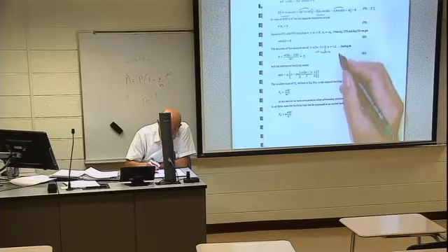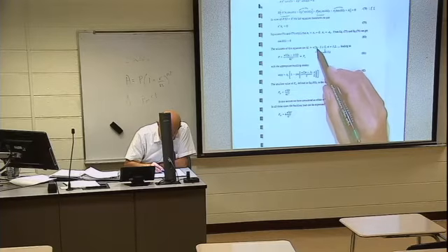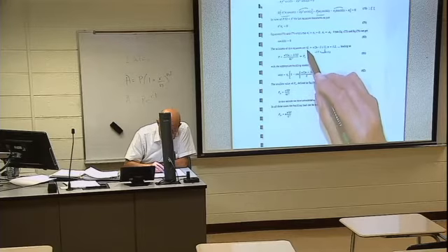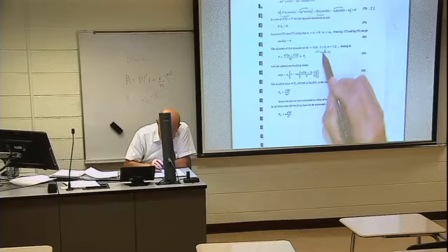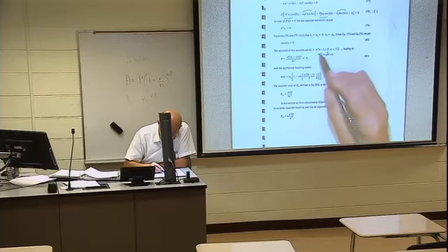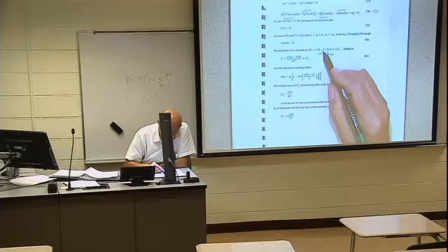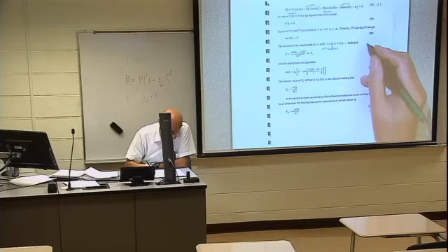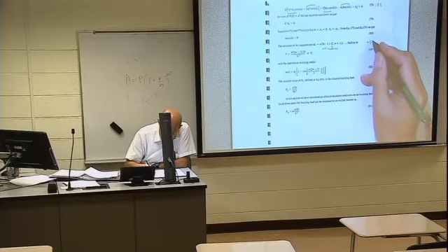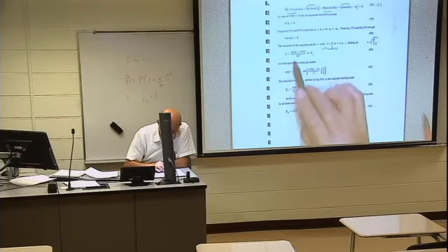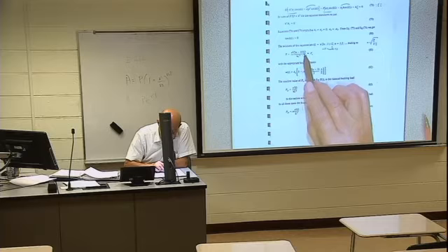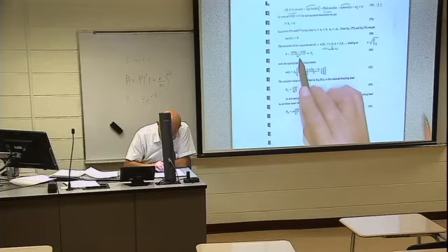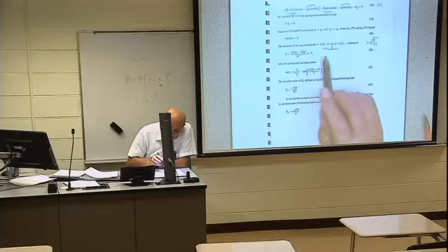For example, n equals 1 will be 2 times 1, which is 2, minus 1 is 1. So cosine equals 0 indeed for pi over 2. Then the second root will be 2 times 2 is 4, 4 minus 1 is 3, 3 pi over 2. So then from here, because k equals square root of P over EI, we get P equals pi squared (2n minus 1) squared EI over 4L squared. So there are many buckling loads.